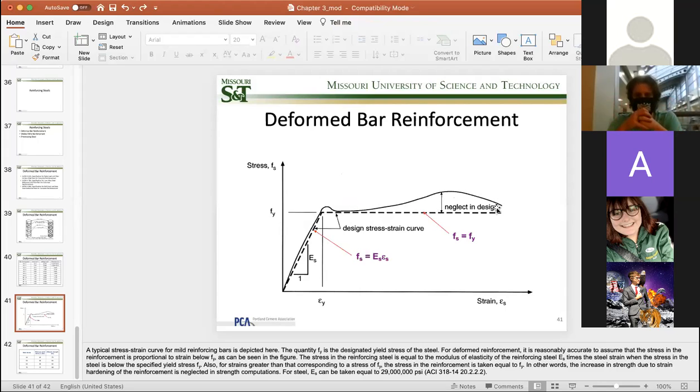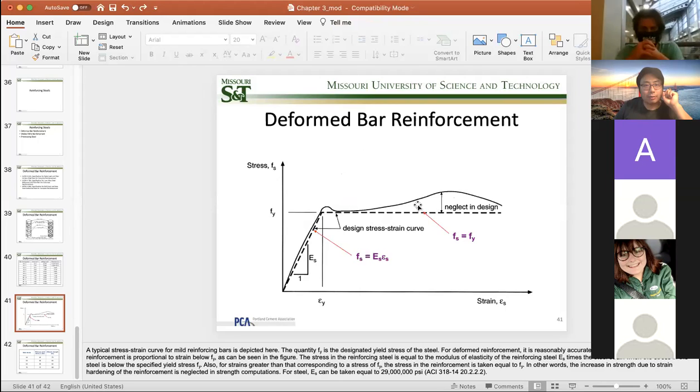Now, really keep in mind here, this curve is for hot rolled steel. Cold rolled steel does not give you performance like this. You will probably learn that from the steel structure design course later, but this is for hot rolled steel. The distinct feature of hot rolled steel is that I can use this dashed line as a backbone envelope of this curve.